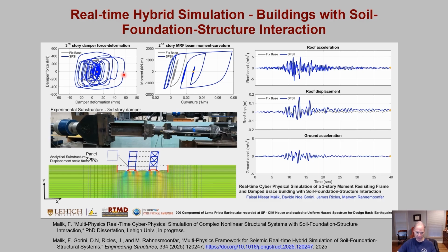So the load path's disrupted. If that doesn't happen, the damper forces are larger than perhaps what you designed for, and the adjacent members may have a problem in the load path. Look at the ductility demand locally. It's about a factor of 8, so we have considerably more damage, and you can tell this after the earthquake, the building's leaning. The owner's going to be furious with you if you were responsible for this.